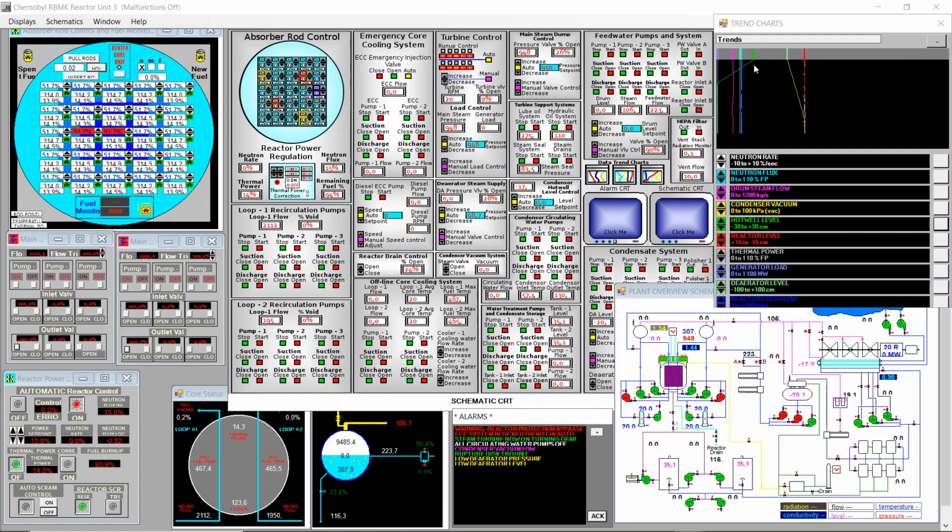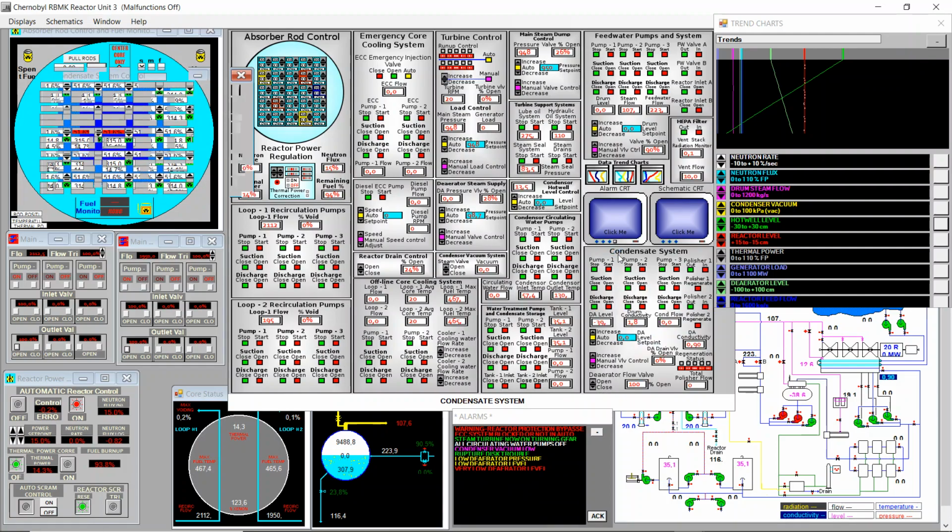And the hot well is increasing back. How is this happening? Where is the water that is filling the hot well coming from? That's crazy. That's crazy. These 3 pumps are off. And I don't see any pump going to the hot well. Let's check the condensate system.